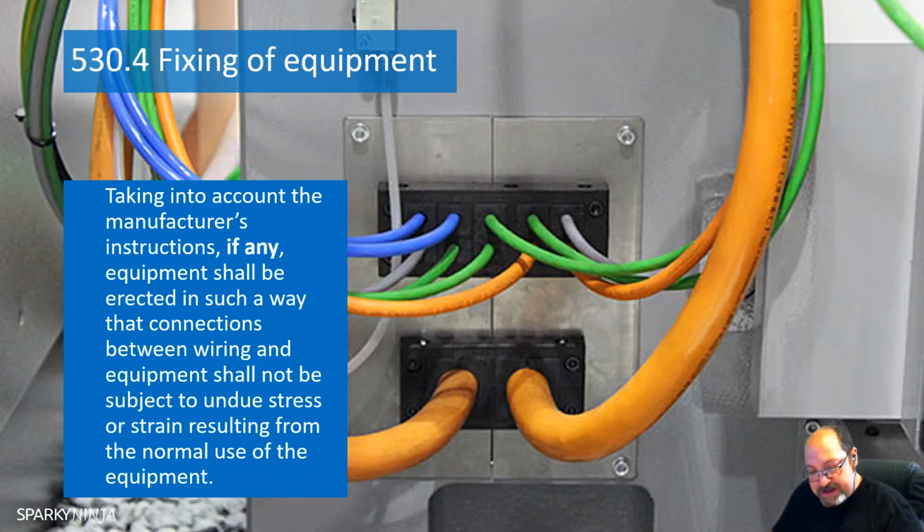Okay, it then says, unenclosed equipment shall be mounted in a suitable mounting box or enclosure in compliance with the relevant parts of BS EN 60670 or 62208 or other relevant standards such as BS EN 61439. Again, I'm not going to go through those standards and the specific requirements of every single one of them because there's no point, but it's got to be designed for purpose. So if you're going to install equipment in an enclosure, it has to be an enclosure that is actually designed to have that equipment installed within it. If your equipment has a thermal cycle, for example, you don't enclose it in something that will not allow a similar thermal cycle during use.